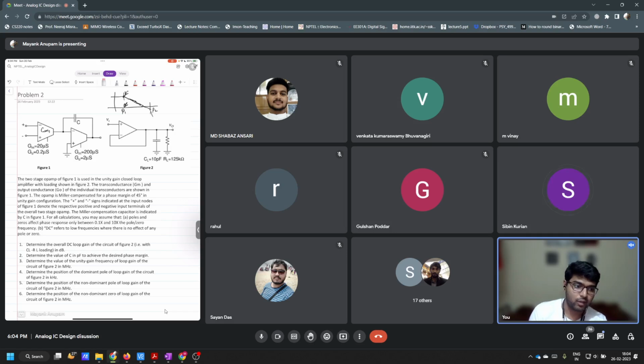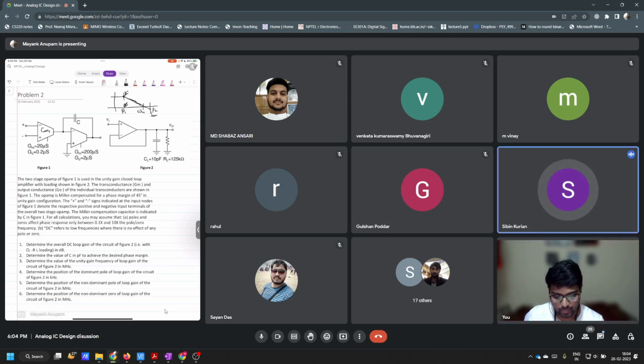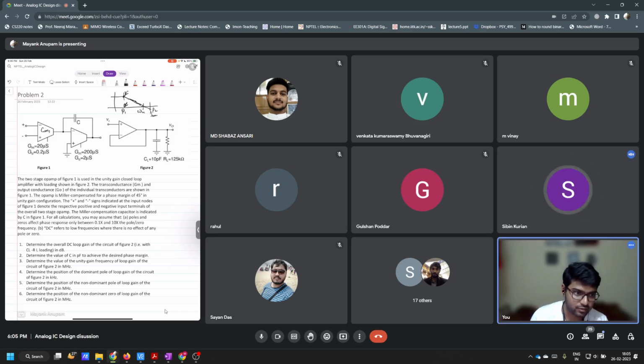If the relative distance between them is large, and the unity gain frequency appears before P2, I mean, clearly here the unity gain frequency is here, right? And it is before P2. Then this approximation is approximately fine. Okay, I understand. Which means the integrator action works for frequencies up till omega u loop, right? Right. Yes. Okay.